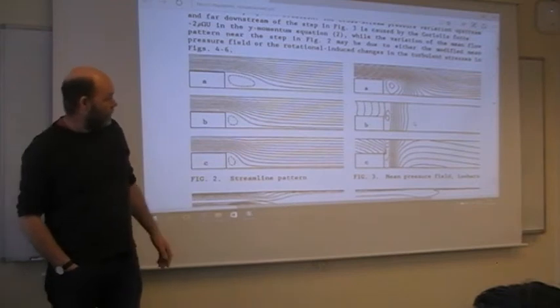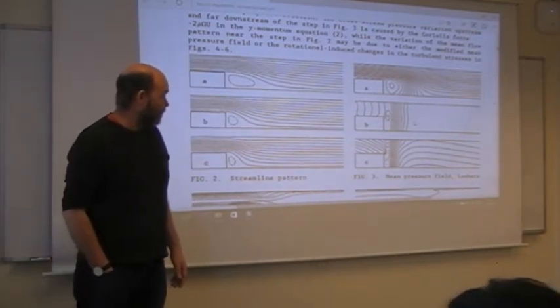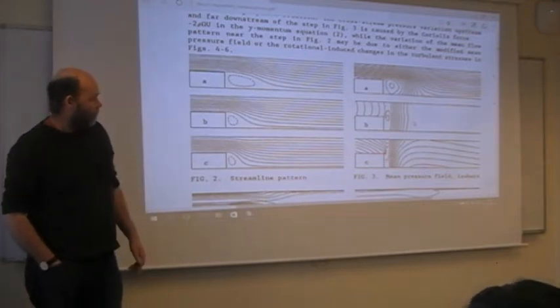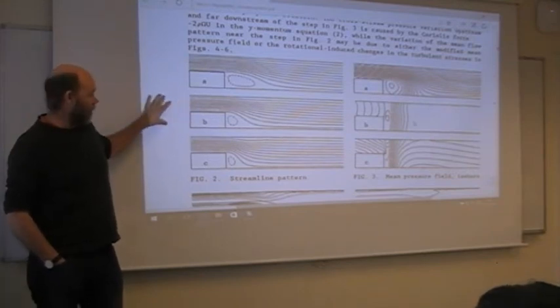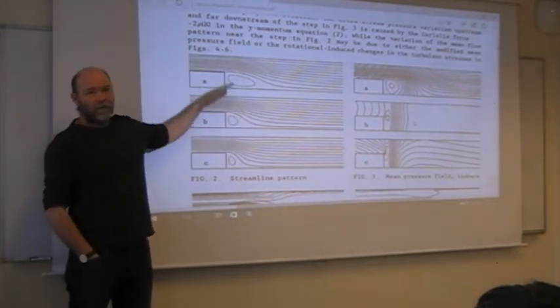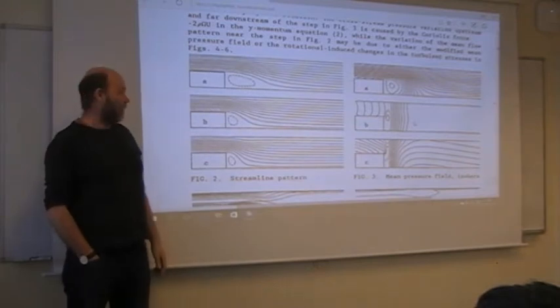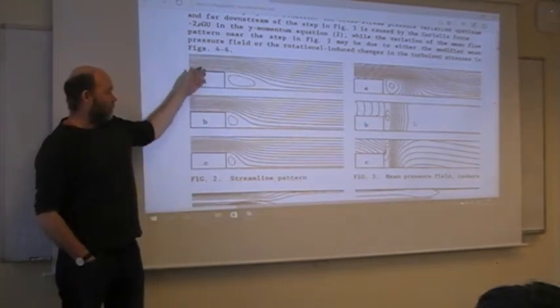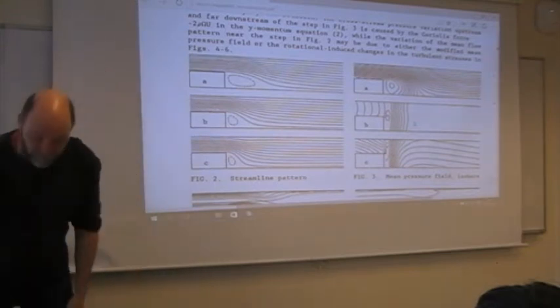So the pressure, not that easy to see the physics there. One thing we can say already, if you use K epsilon only, you will get the center, the case B. It doesn't see the rotation at all, unless you can do something tricky with the K epsilon model, or else you can't really see the effect of the rotation whatsoever.